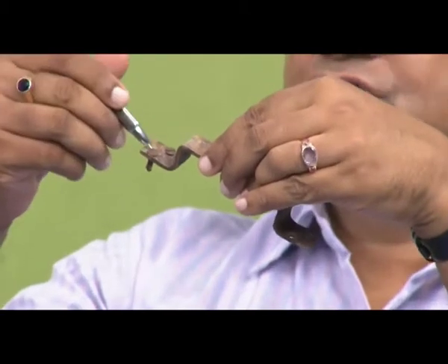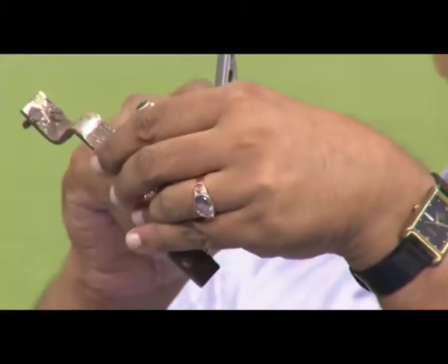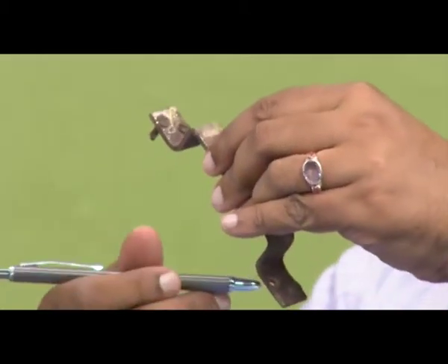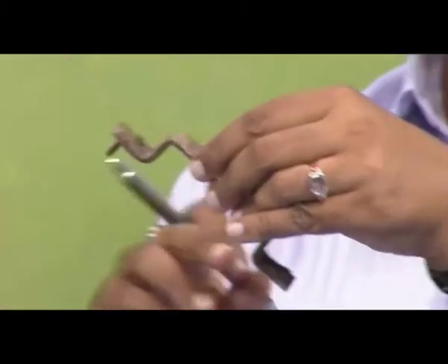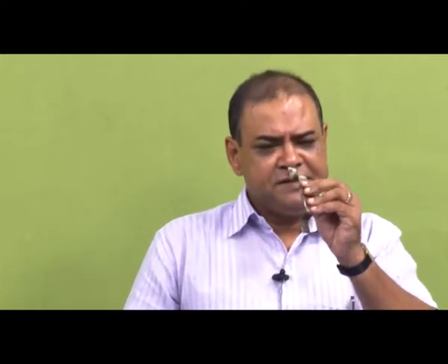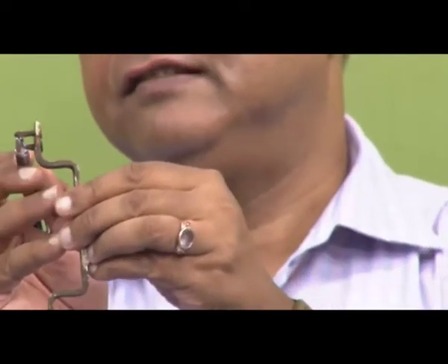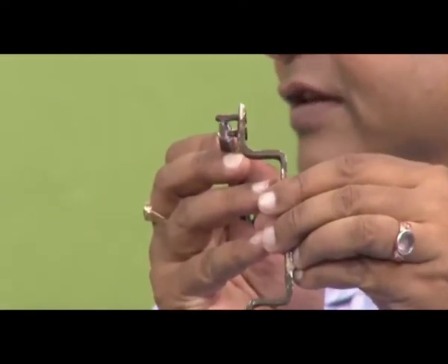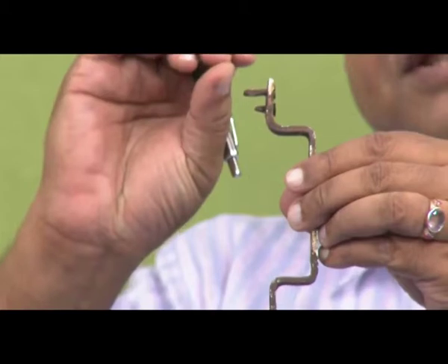This is a metal object, and there are 2 screws here and 1 screw here. Almost similar type of screw. One screw is missing because when I pulled it up, it got lost. But if you see this particular segment, on the screw top there is corrosion. I am not saying that there is no corrosion. But interestingly, if we see the other part, it is a kind of exfoliation. The rest of the screw has swelled, and this swelling has happened because of the iron hydroxide formation. This is a rust, basically the red rust.